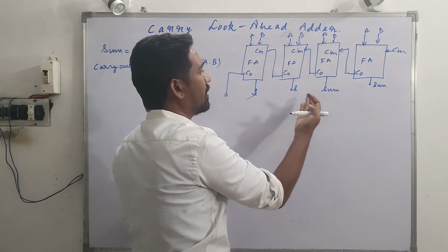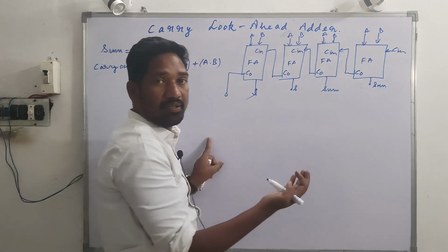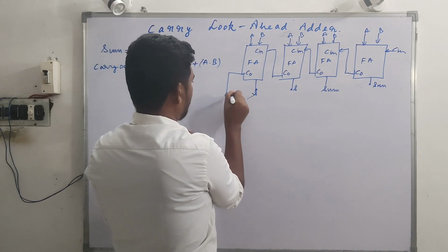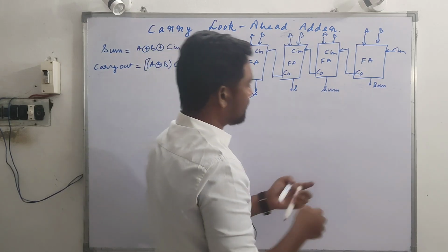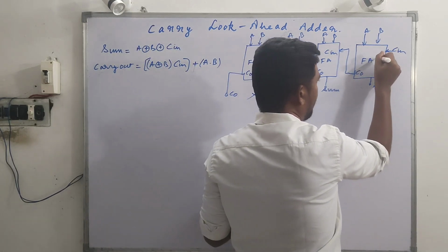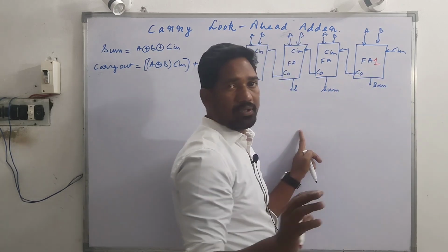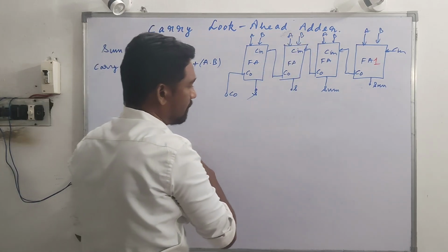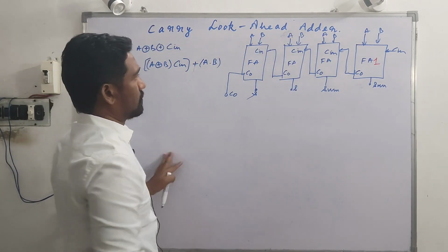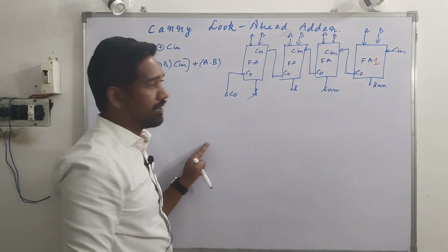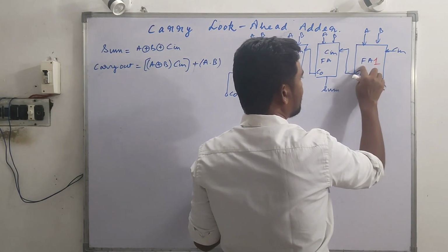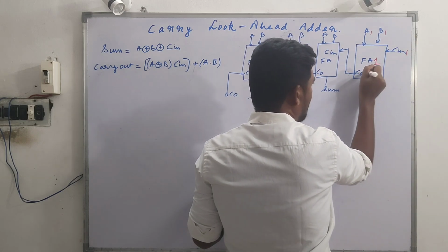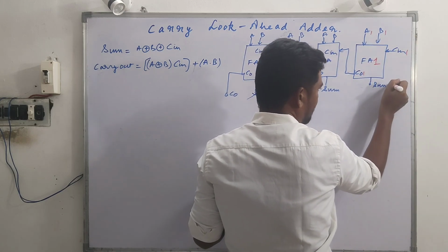This is the arrangement for a 4-bit parallel full adder. From the picture, from this array, this will be the Cout. If this is the first stage, full adder 1, here the important points to be remembered arise, to avoid confusion in the bigger Boolean expressions we come across in the working of a carry look ahead adder. If this is the first stage, the inputs are A1, B1, Cin1, and the outputs are Cout1 and sum 1.